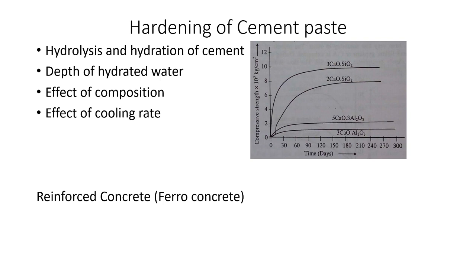Concrete is brittle, it cannot bear tensile load. Similarly, steel alone is not very resistant to weather. Hence, it is necessary to reinforce the concrete with material which can support the tensile load. So steel rods with rough surface are generally used in reinforced concrete. That gives the strength to the construction.